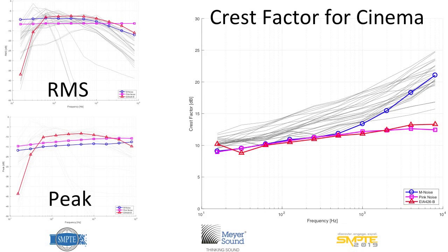And so hopefully you haven't been listening to me during this slide. I'm just babbling. You're just looking at the trend here and how remarkably similar it is, even though this is a small sample of cinema audio, we've seen a large sample of speech, we've seen a large sample of music. We have our intuition that crest factor increases with frequency, and every sample of actual content we look at, the crest factor, without exception, increases with frequency. Really, the only surprising thing here is that our test signals do not. That's really the most surprising thing.